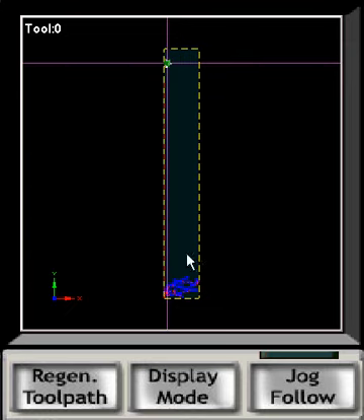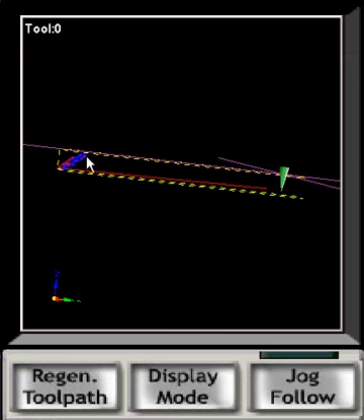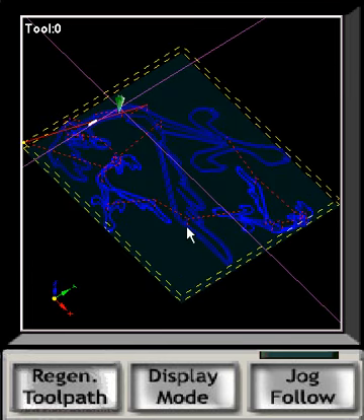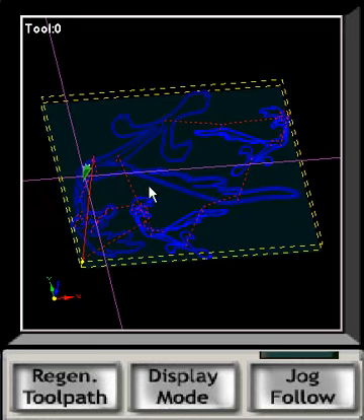I'm now going to regenerate the display. What you'll see is that my toolpath is way down here and rotated at 45 degrees. This is because this toolpath display takes into account rotational changes. So make sure when using this version onward, if you want a proper display, that you zero your rotational axes before you load your job or afterwards and then regen. You'll have to regen if you reload a program and your rotational axis is not zeroed. So take note of that particular issue. And here's why.